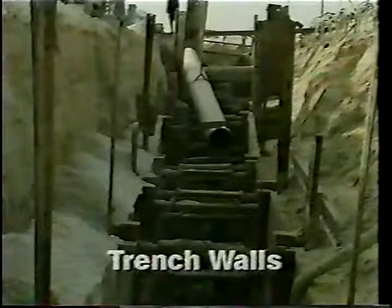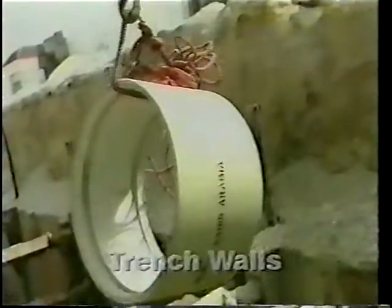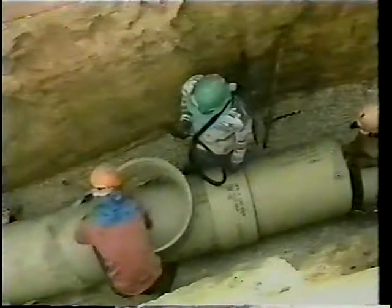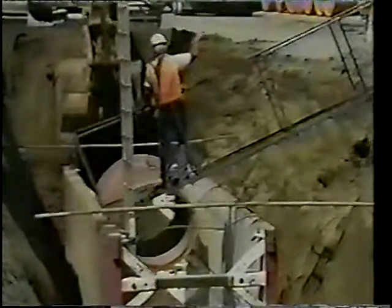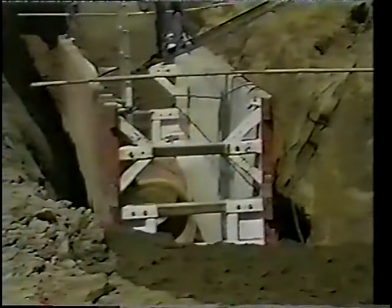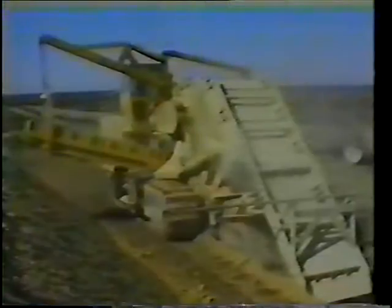For all pipe, the trench dimensions depend on site conditions, the soil encountered, the type of pipe, and its size and shape. For rigid pipe, the trench should only be as wide as necessary for installation and backfill of the pipe. Here, a 96-inch ladder trencher cuts the trench for a 60-inch concrete cylinder pipe.